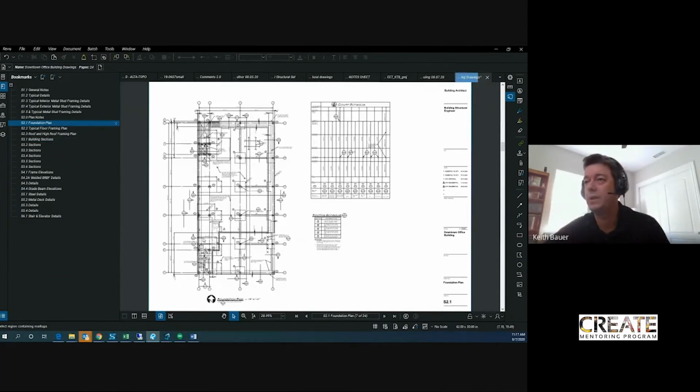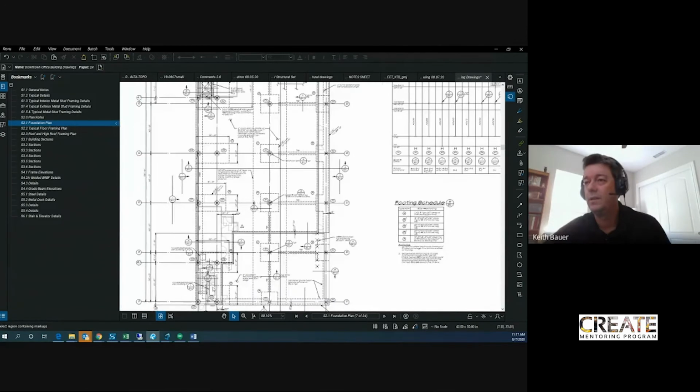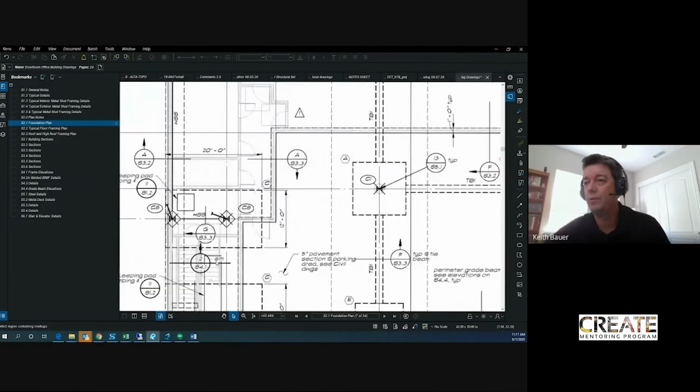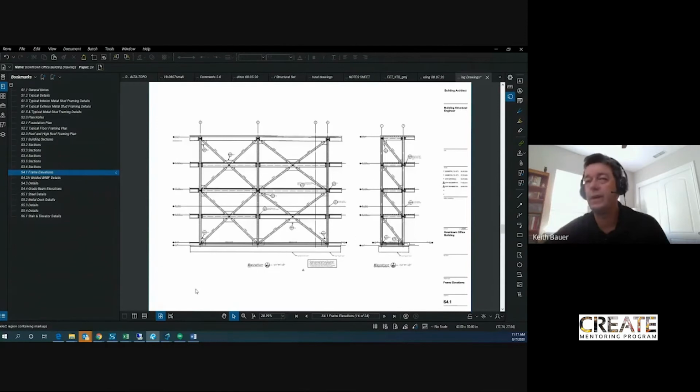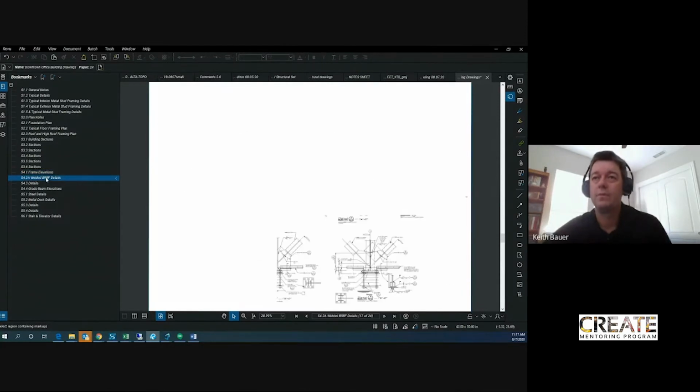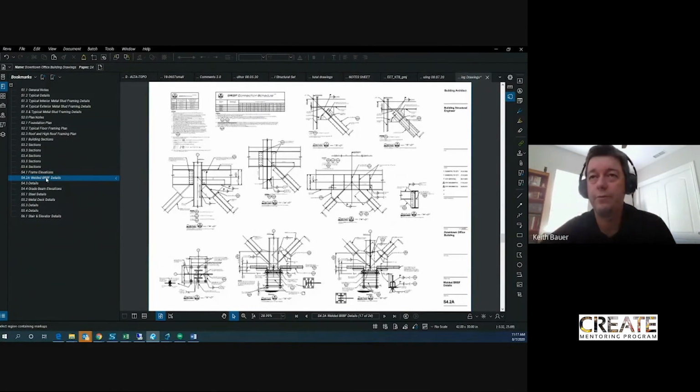Going back to the foundation plan, you'll see that there's this elevation callout, 2S4.1 similar. Sim is similar. So it's pointing at this area. That's what's being shown in this view, is that frame. We talked about 4.2. If you see any references to 4.2, it really means 4.2A in this project, because I said we had two alternate types of details. There's a 4.2A and a 4.2B, and we were leaving it up to the contractor to choose which one they wanted to use. Ultimately, they decided they're going to use A, so we just took out the other sheet.